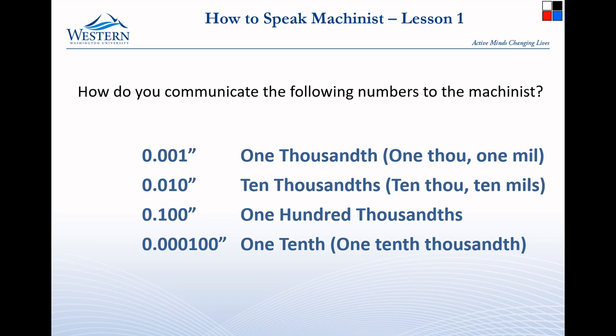We're going to have to be real careful with our thermal control. We're going to have to warm up the machine before we use it. We're going to have to not let the coolant get super hot, all kinds of things like that. This number, oh, the possibilities are just endless.